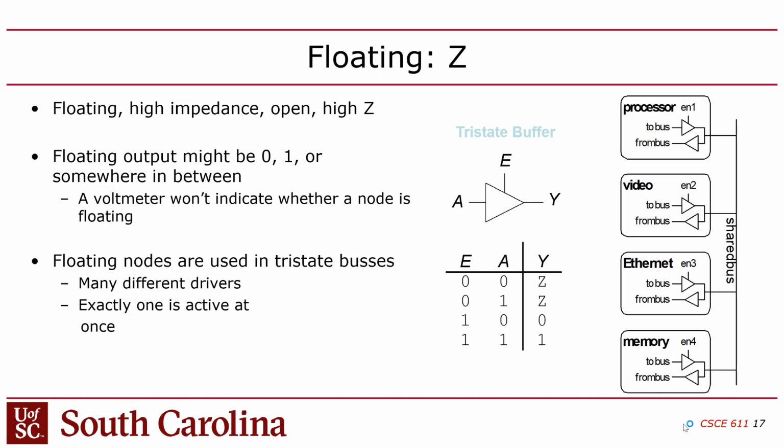So to summarize, Verilog uses 4-state logic. Basically, you could have a 0 or 1 or a Z or an X. VHDL, which is another HDL, I'll talk about more in a minute. It has some additional, I think it has 6. VHDL uses dash for don't care, and it uses U for uninitialized register. So I think VHDL has 6 symbols. Verilog has 4. I wish Verilog had the U, because I think that's useful to know if you have an uninitialized register.